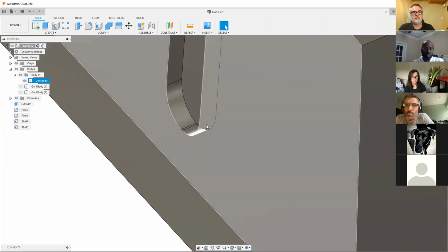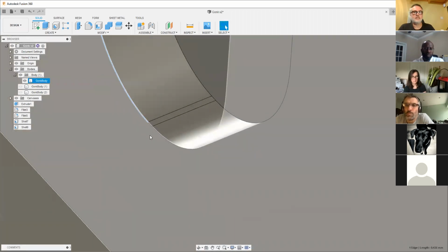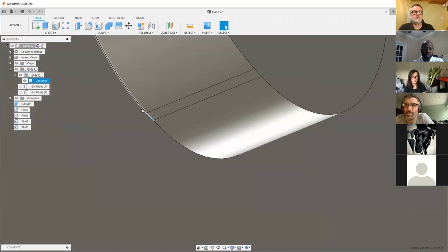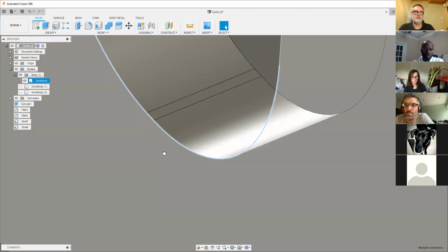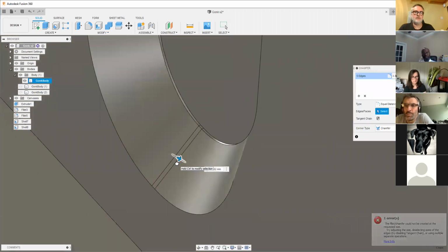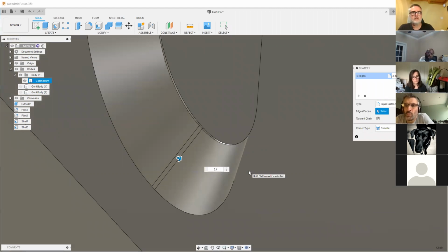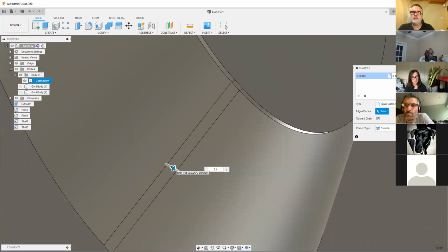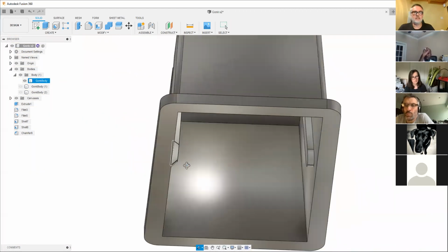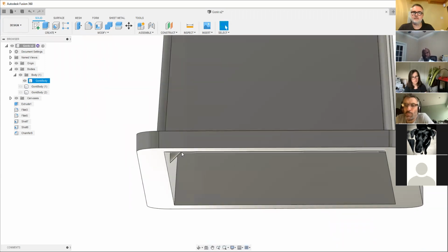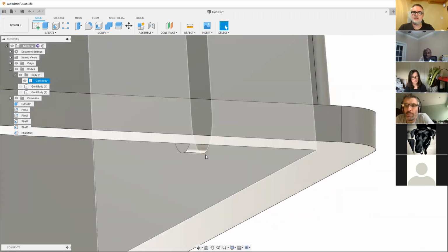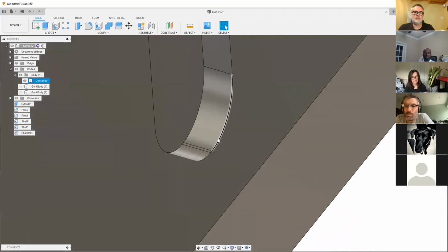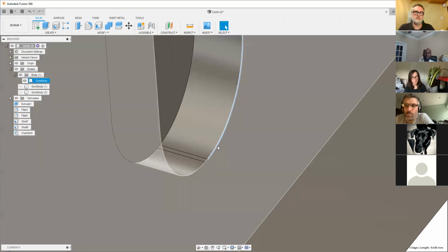These overhangs here, what I would do is highlight this edge, this edge, and this edge. What I'm going to do on that is use a chamfer to see how that works, like that. Pull it out to whatever that'll be, 3.4 probably. Click. Right, you can get a little bit more on there. Click OK. So what that means then is as it's printing up here, it's only printing this out at a 45-degree angle, so you don't need any supports. Whereas if you printed it on this side, this is printing a piece straight out into thin air, which means it would just drop somewhere. And we don't like support, so we'll do the same on this side.